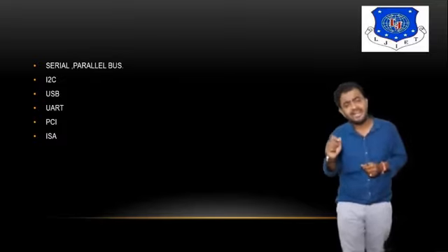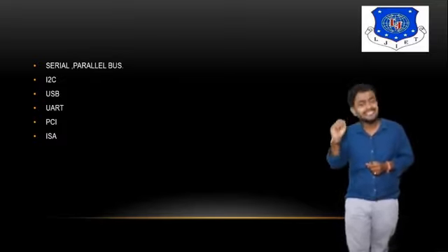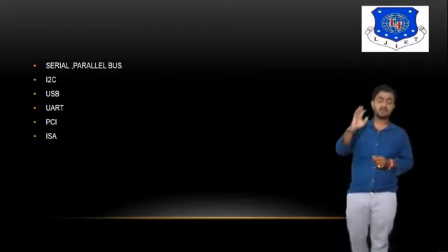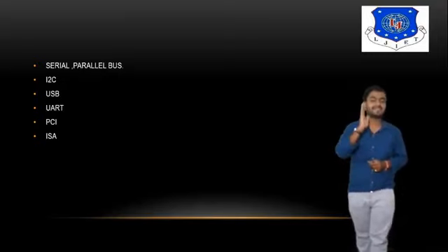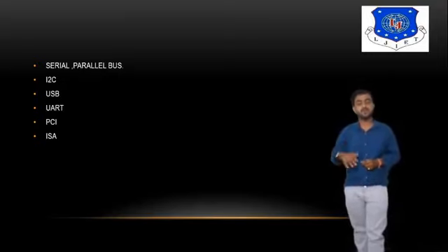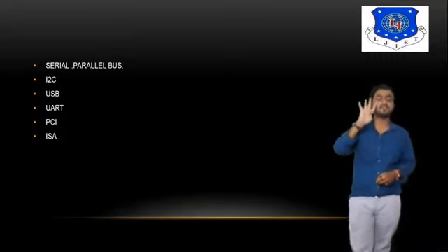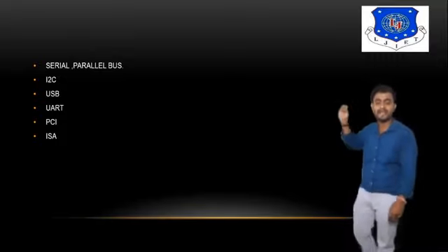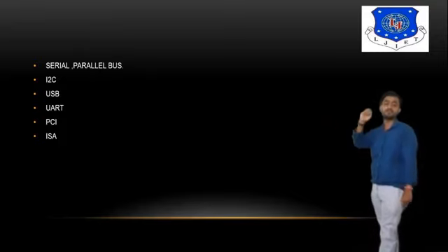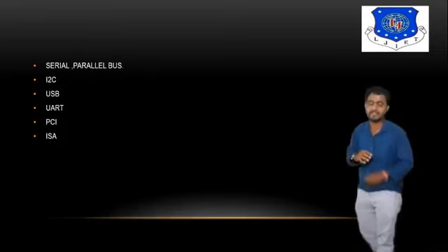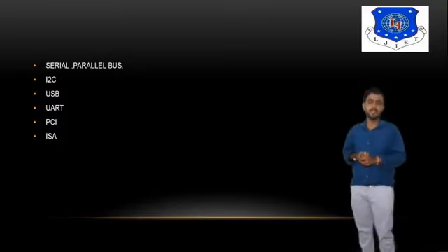If you connect a normal LCD with your microcontroller, then ultimately it takes 4 data pins and 2 control pins, so it occupies 6 pins. And if you connect an I2C LCD, then it requires only 2 pins. So you can save 4 pins. So I2C is one of the best examples when you have to communicate with a number of peripherals such as sensors.